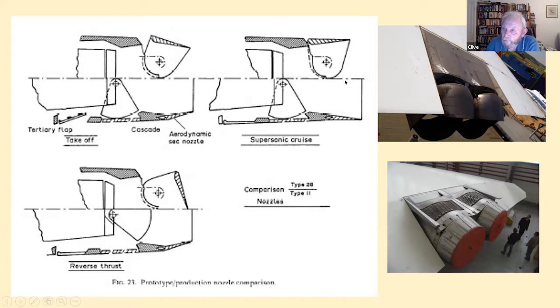In the course of the production, we changed from that to the nozzle known as a tuyere reverse ovale, which is the aft reverse nozzle, in which the thrust reverse was obtained by a pair of these buckets coming round and shutting, and in the supersonic cruise condition, we then had a simple ejector nozzle.